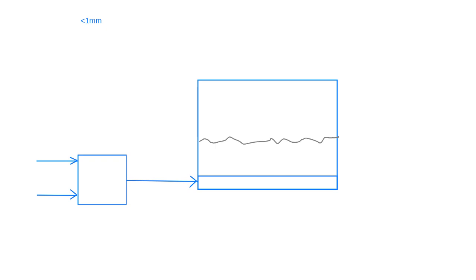So a fluidized bed is a bed of small particles, call them less than 1 millimeter particles, and you are bubbling gas. You are forcing gas through holes. There are holes in this plenum at the top that allow the gas to go through, and then you will get gas bubbles in the fluidized bed. Gas bubbles tend to get bigger towards the top.